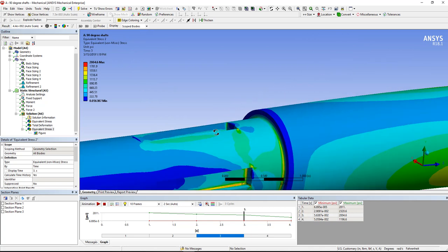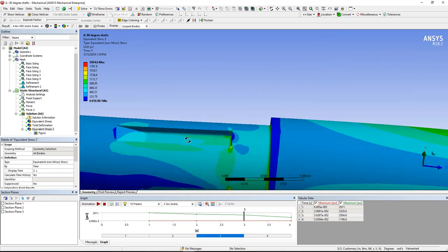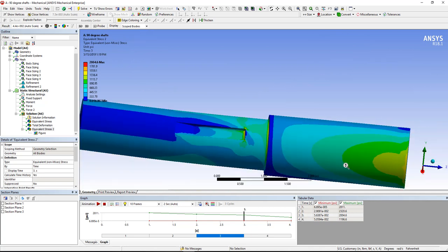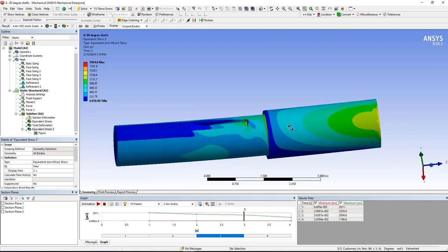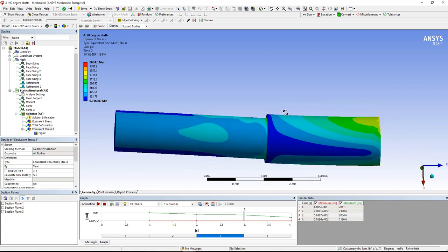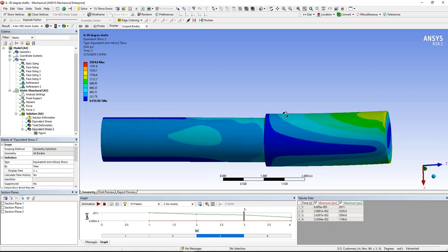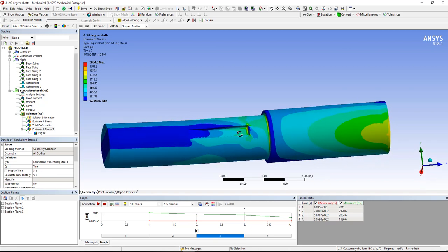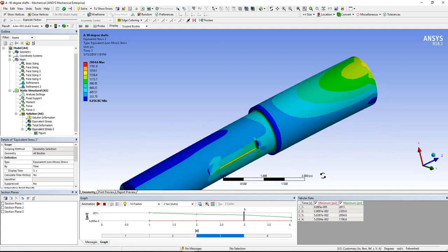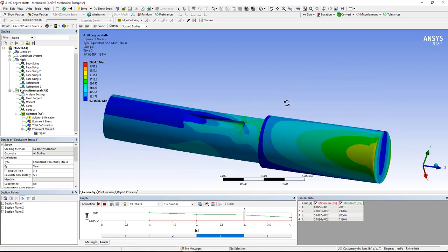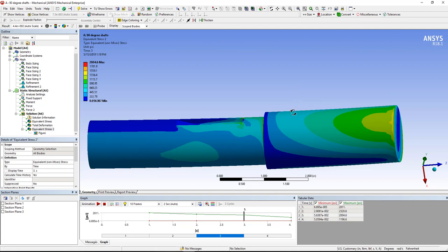So your question is, first of all, are these a good representation? Is that an adequate stress state? Is it the right orientation of the moment, where the stresses from the moment are going to add to the stresses in the fillet versus subtract from it, or not have any there, as the case may be? And then compare the two geometries.